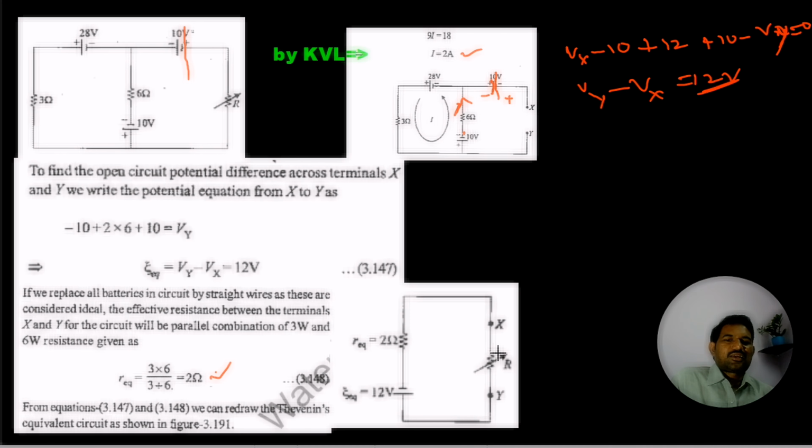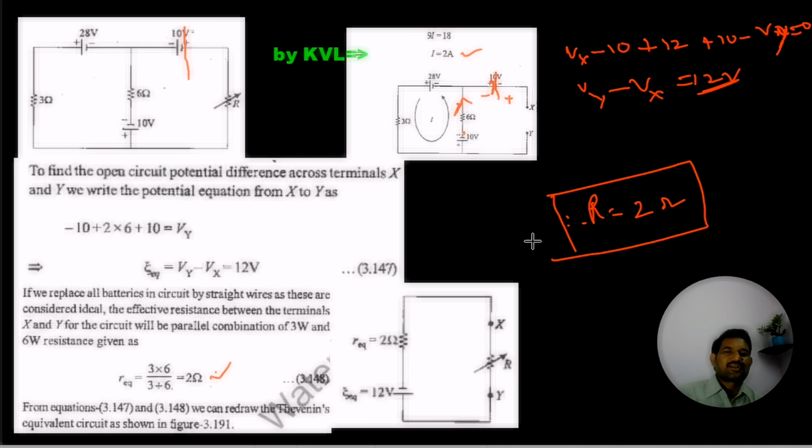And so in that case what we can write is that the current or power in that circuit will be maximum when the external resistance is equal to the internal resistance. Therefore this R value should be equal to this 2 ohms here. So that is our required resistance. So is it clear? When such a complicated circuit is given and they are asking the condition for maximum power, this is the procedure you need to remember. If you are able to calculate the internal resistance directly, you can calculate that internal resistance and equate that. Or otherwise, this will be the procedure here.